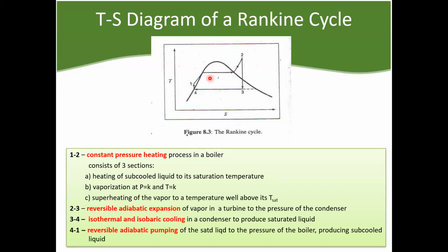And what do you notice? Initially in the Carnot, we're just operating in a square inside the saturated curve, right? But since there's superheating, now our outlet from the turbine is closer to the saturated vapor line, meaning there's less liquid and more vapor.